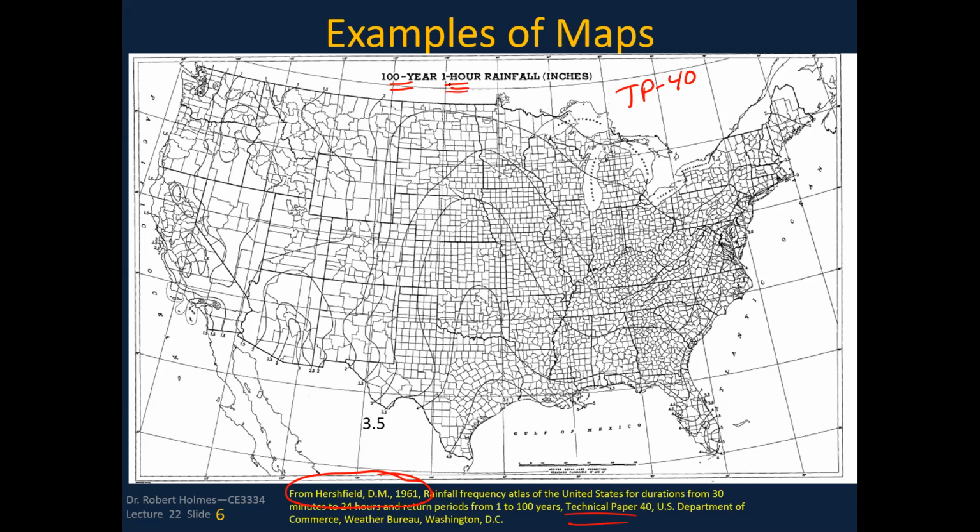So this is the 1-hour storm values for the 100-year flood or the 100-year rainstorm. You know, they would have a series of maps for the 50-year frequency, and they would have 1, 2, 6, I'd have to look it up, but they'd have all these various frequencies, I'm sorry, durations that would happen. And so this is for the 100-year 1-hour rainstorm.